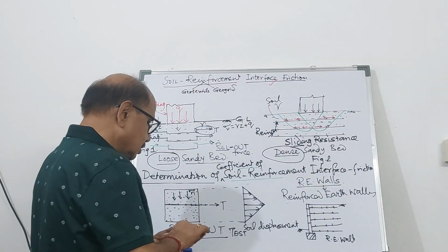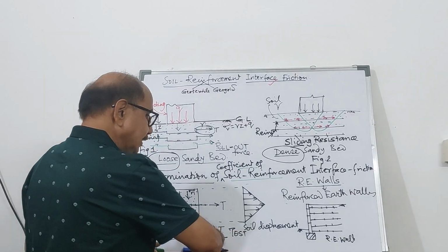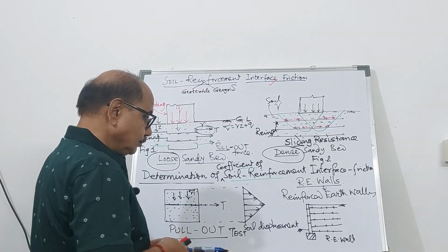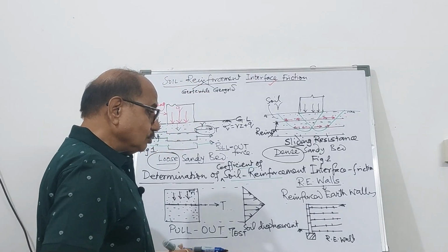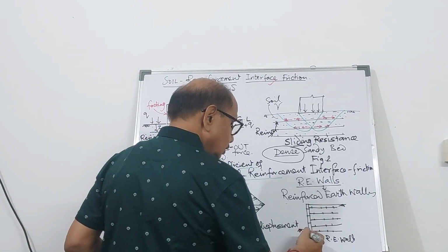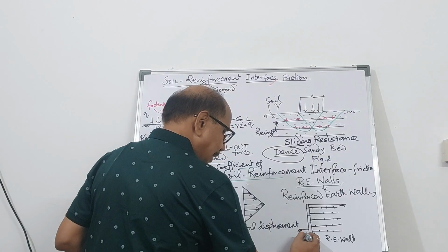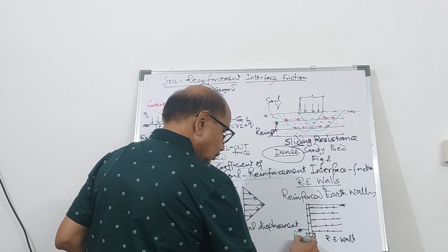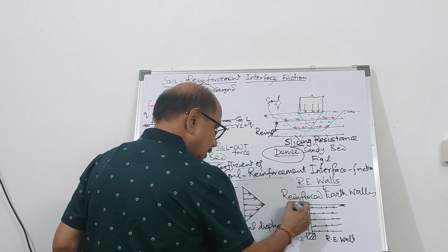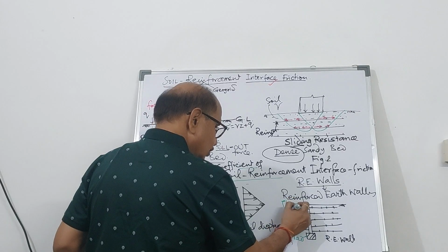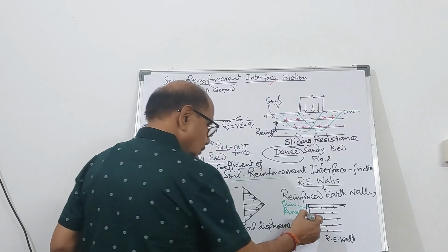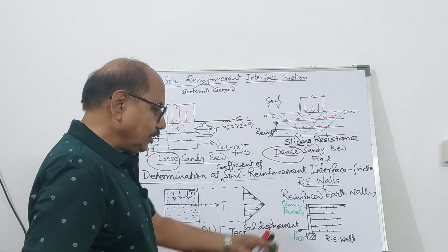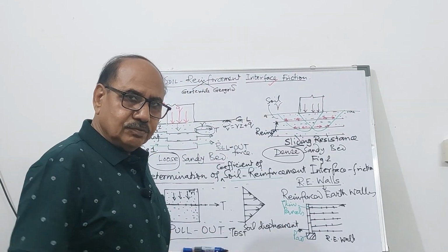In RE walls, friends, wherever you have a weak ground, you want to spread the load. Here, it's simply a pad, because these are thin panels, facial panels, which are quite thin. As a result, you need a pad, not a heavy foundation.